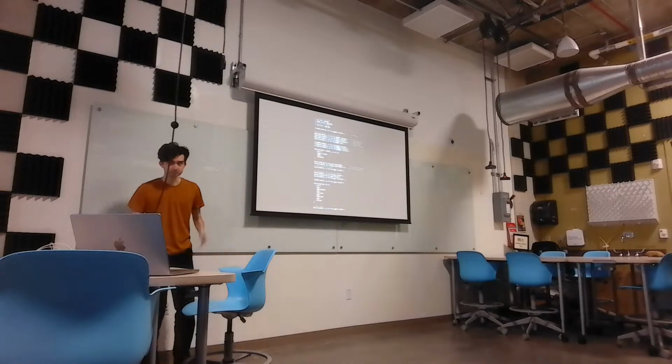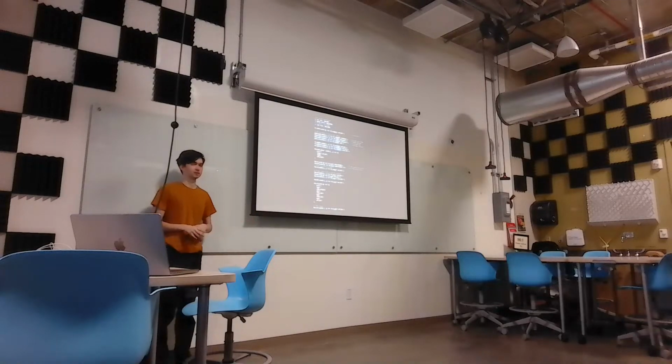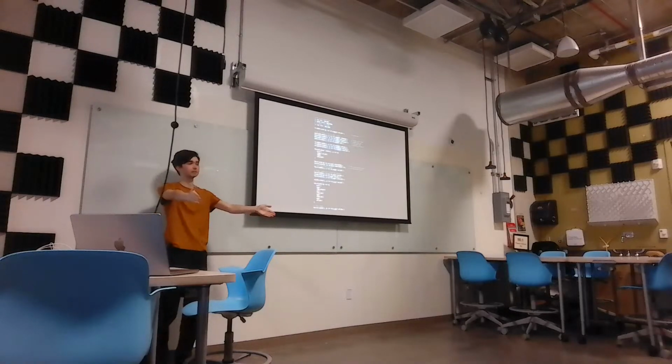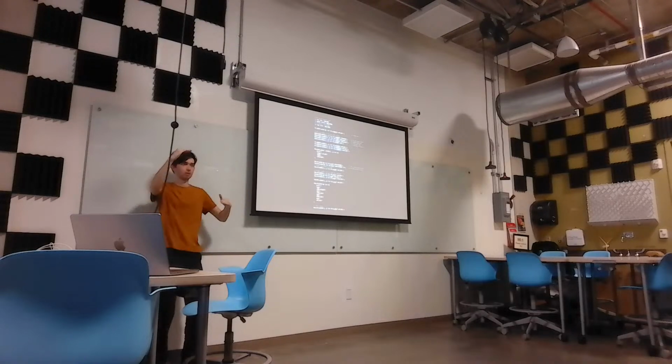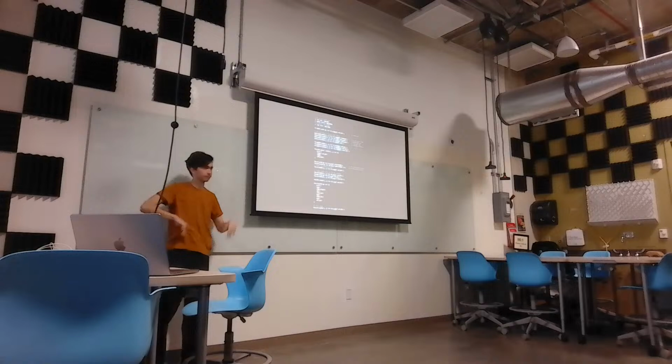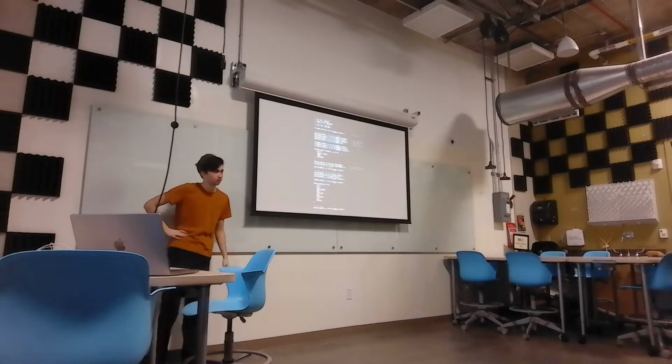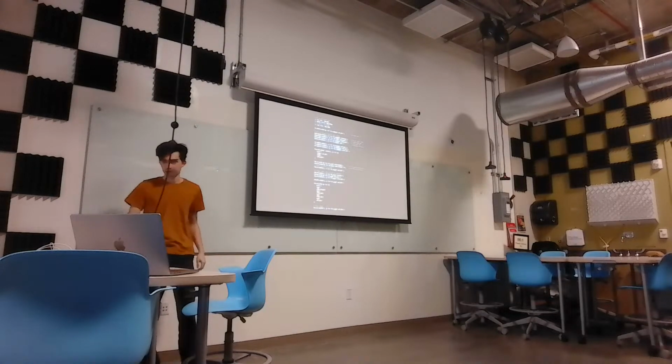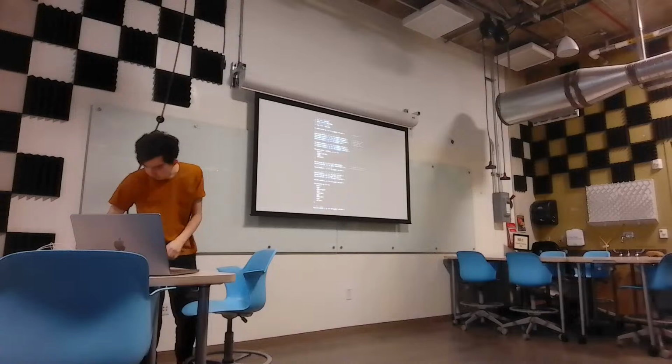Opposite meaning, okay, I feel like I didn't make this super clear. One PWM signal corresponds to one FET. The other PWM signal corresponds to the other FET. We need them to be like this, or like this. Can you go back to the picture and demonstrate why both of them on would be a bad idea? Yeah. I will do that.